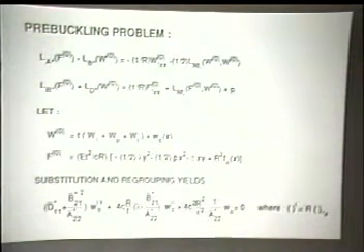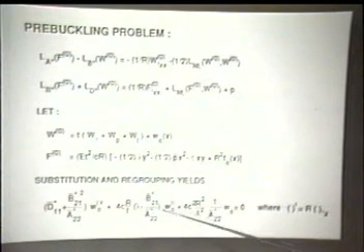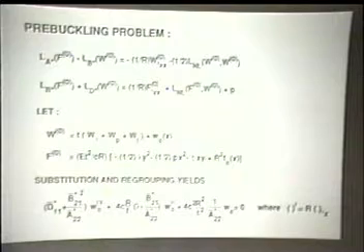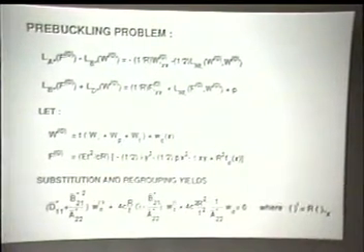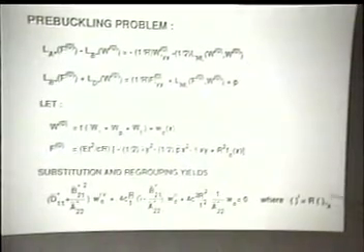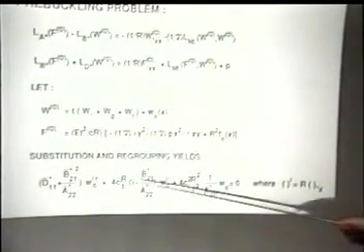So essentially, with these assumptions, we can reduce these equations to one fourth order ordinary differential equation in W sub 0, first derivative, second derivative, etc. Notice the primes are normalized with R. Now, this is a constant coefficient equation. So you can write down its solution in terms of exponentials. I do it numerically because it's more convenient, but there is no problem to it.